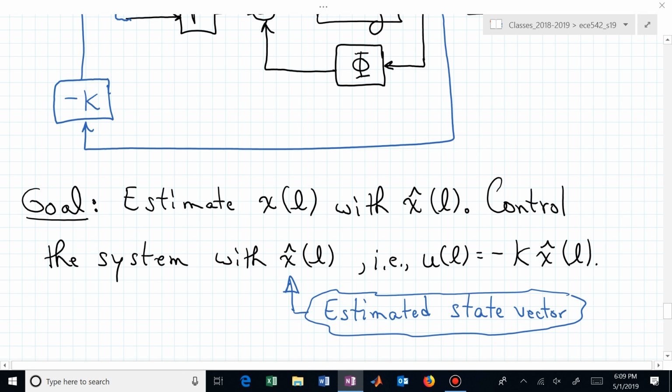That then just says, you know what, I already have x sub 1 and x sub 4 and x sub 7. I don't need to estimate those. I can measure those. Let me just measure or estimate the ones I can't measure, and that's now a reduced order estimator.